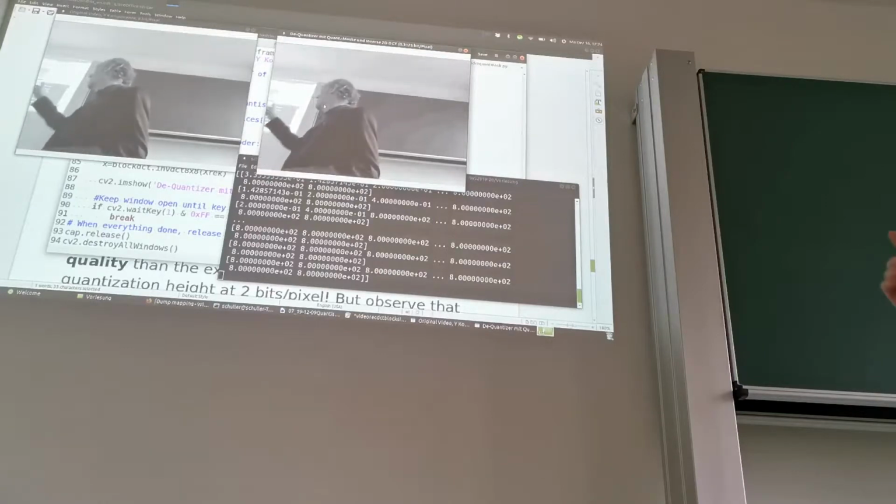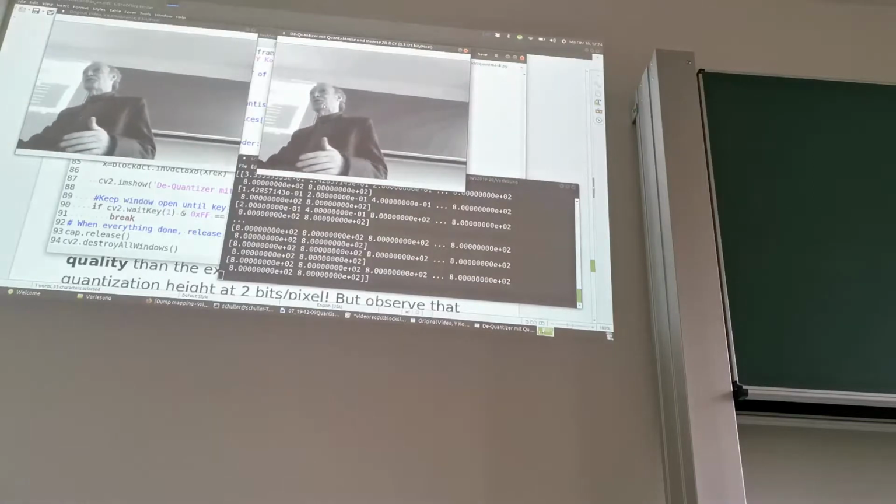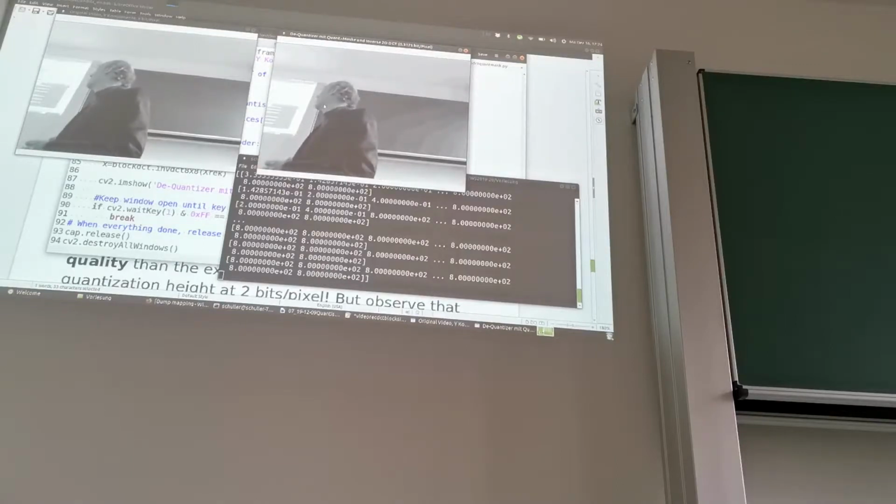And again, here I dropped all the high frequency coefficients totally. Most of the coefficients are gone, but these are all the high frequency coefficients, and the eye is not really looking for those high frequencies in an image. So we still have quite a good compression, but at a much higher quality now, because we put the bits where the eye notices them.